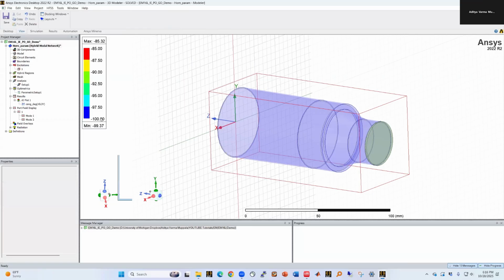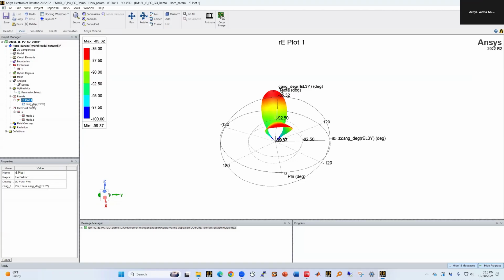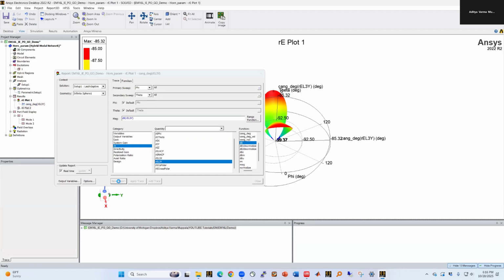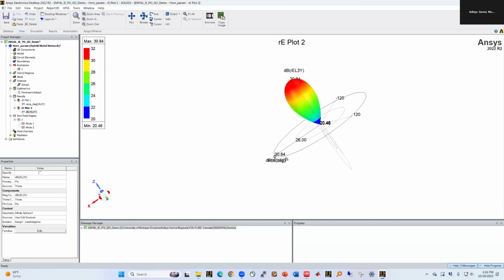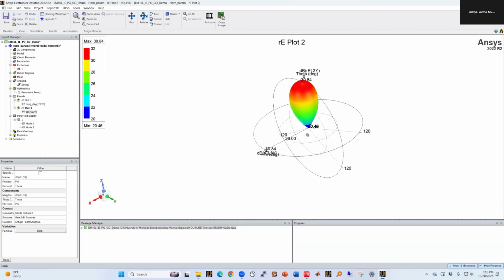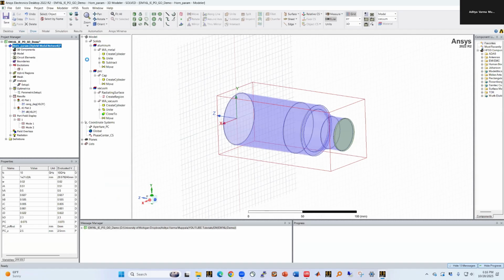It's important to keep in mind that you should be a little bit careful about selecting the phase of different cuts and optimizing over them, because you need to make sure that you're choosing the right polarization. And you can check that by looking at the dB value of these plots. Okay, so when you plot your polarization, it should be a nice beam like that. If it's not a beam like that, then you've done something wrong. Okay, so we know where the phase center is. Now we can go ahead and design our reflector. So let's do that.